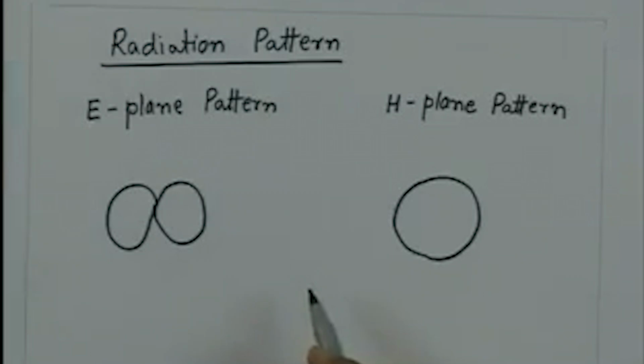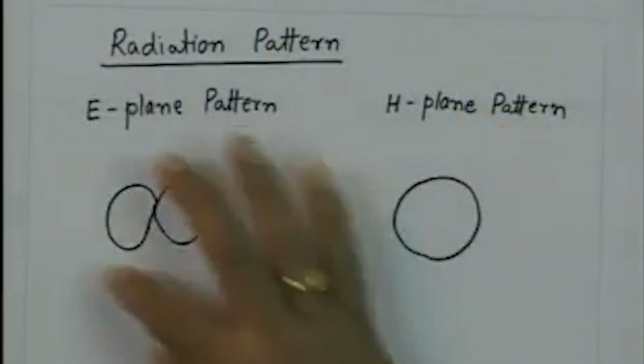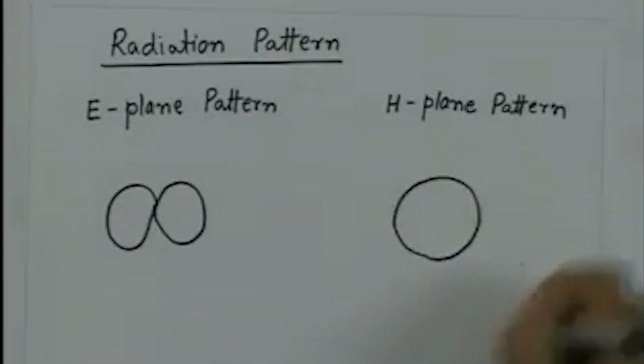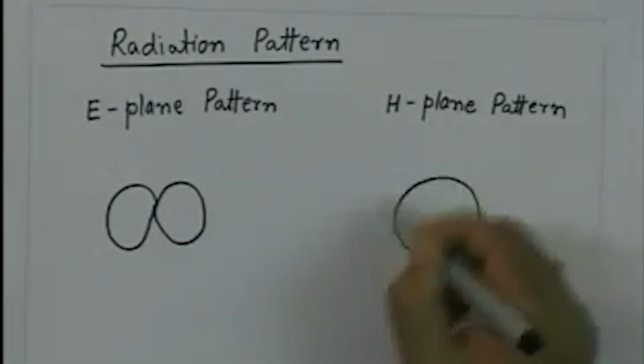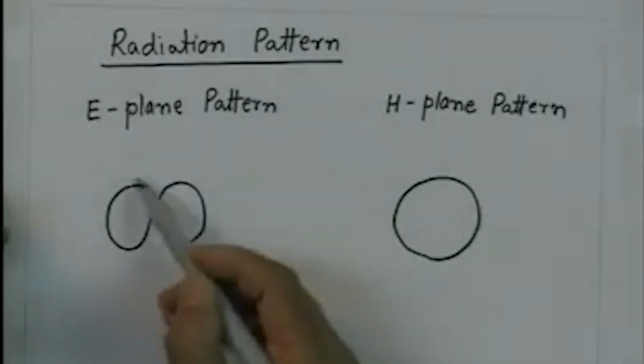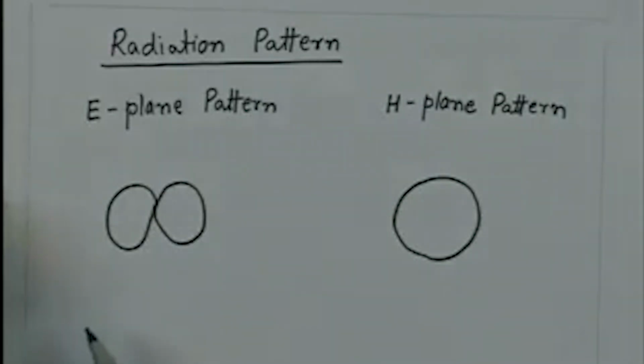Generally, when we discuss antennas, since this figure is very simple, most of the time the radiation patterns are given in the E plane, which is the complicated one for the Hertz dipole or for a linear dipole. Because of the circular symmetry, the H plane radiation pattern is always a circle. So in the books we see the patterns like this, and it is implicitly assumed that we know the H plane radiation pattern, and that it is a circular pattern.